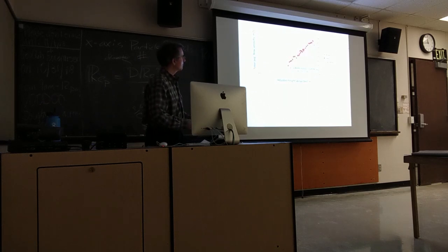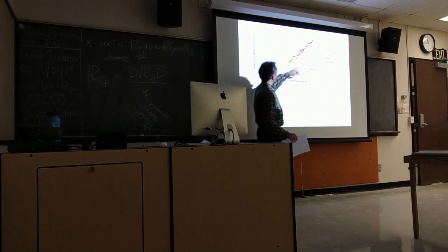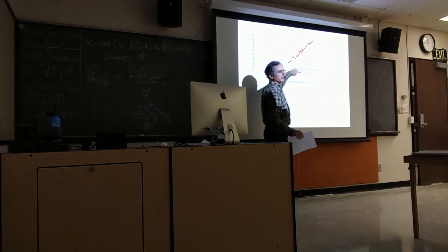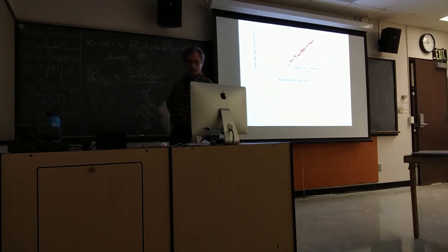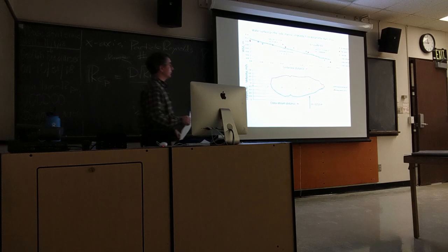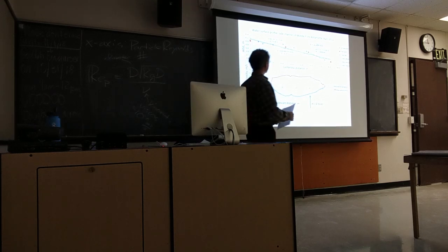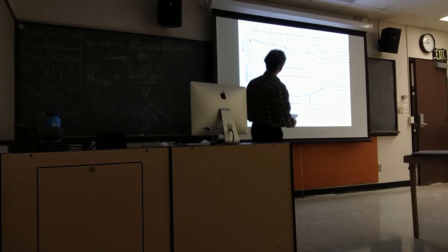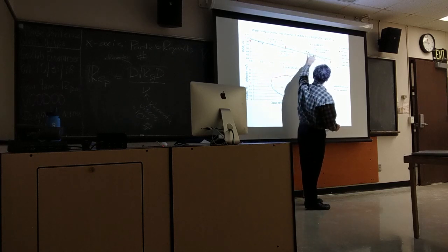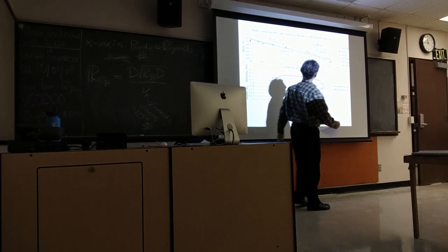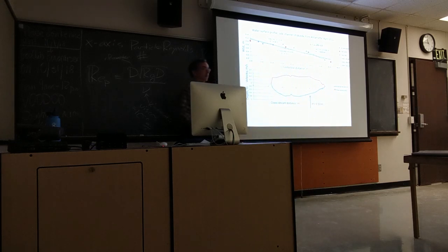So from this constant here, I can figure out what my shear velocity is and therefore what my shear stress is. And I will tell you without writing it that it's 12.5 pascals. Now, I've also had students survey the water surface, and from that come up with this slope, at least for this part, of 2.28 times 10 to the minus 3.